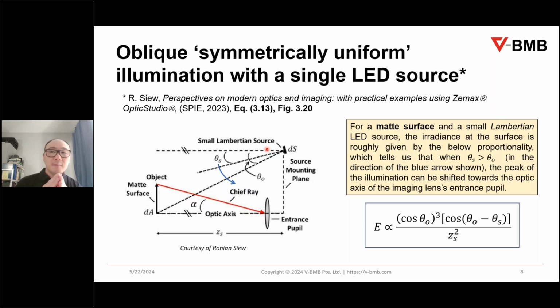And if the plot is symmetric, with a peak intensity at the center, and if you go out 60 degrees and the intensity drops by about 50%, that's roughly Lambertian. A Lambertian source will have that kind of property, and optical engineers love that distribution because the mathematics is very simple with Lambertian sources. So assuming you've got that kind of LED source, we're looking at this diagram sideways. I'm putting the camera's pupil, the camera's iris, on the side here, and the object you're trying to illuminate on the left side here. And you've got a source.